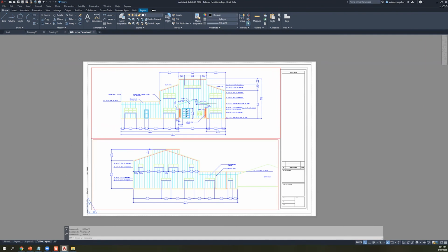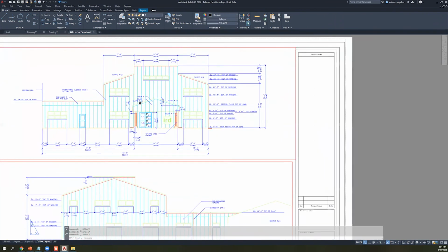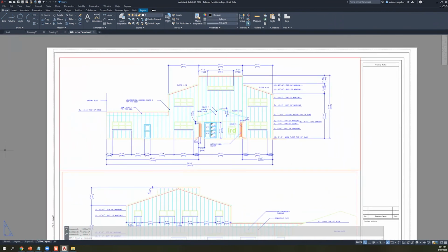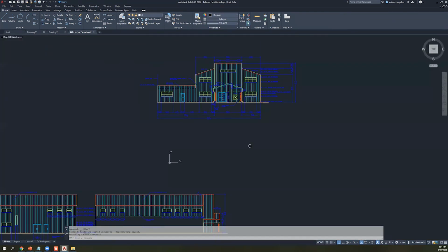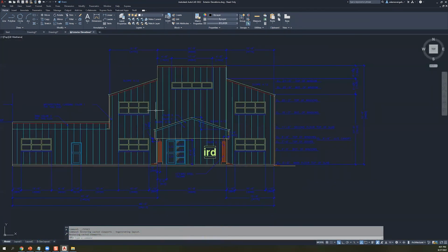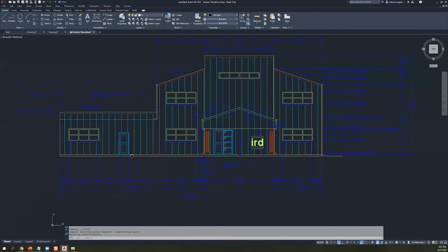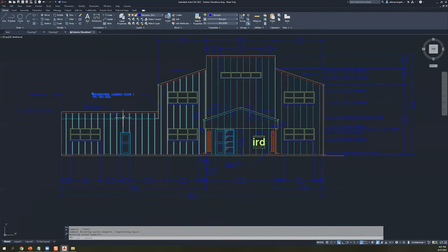And then from here, I should also mention just a little bit about annotations and stuff like that. I always mention this one just because there's a lot of different ways to approach this, and it'll depend on how you want to do it exactly. Like I mentioned previously, these annotations that you see on screen over here are in model space. And so by default, if you're going to do annotations in model space, it's great. It's no problem. Just make sure that your styles are scaled up to match a one-to-one model space scale,